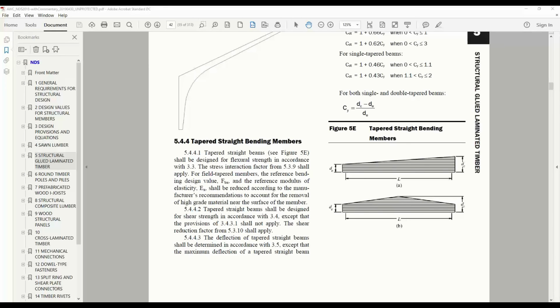We just use phenol resorcinol for the glue lines, and we use a melamine resin for the finger joints, because I don't know why. I think it has to do with curing them quickly in the radio frequency tunnel, so we can use the material faster than having it sit around all day.